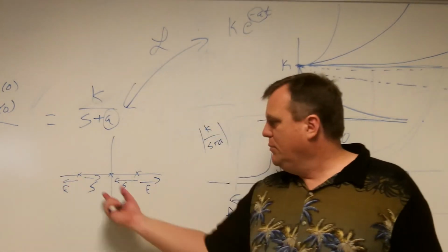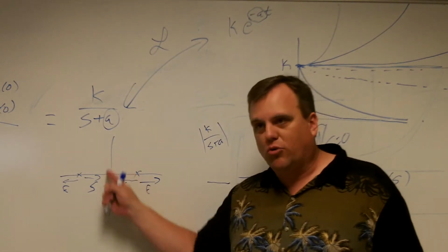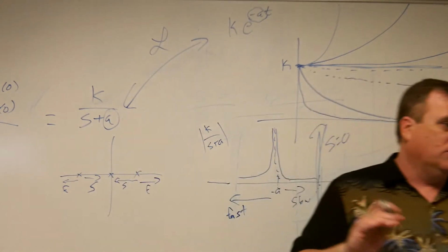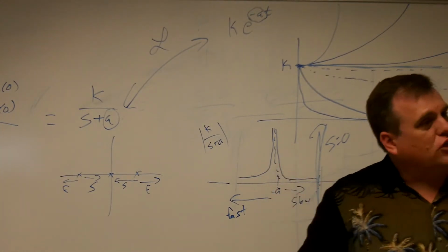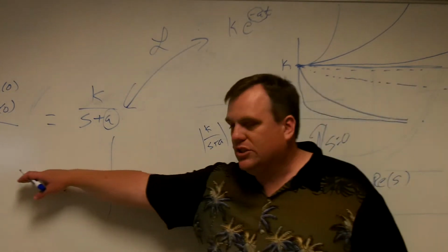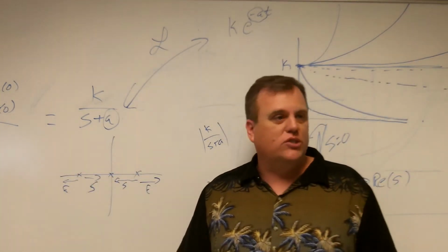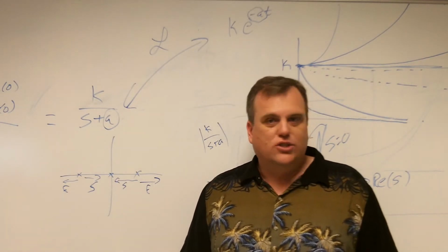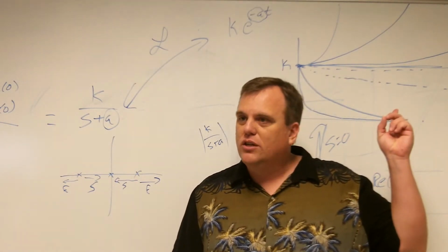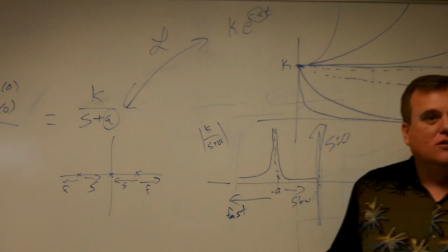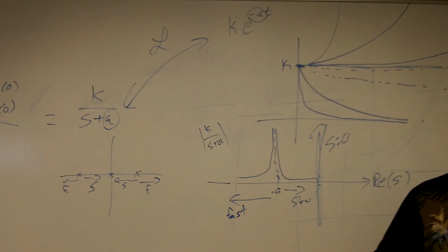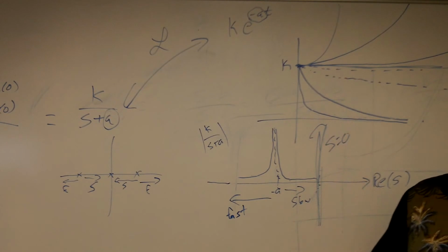So in between damping slow and growing slow, right at the point where they meet, it doesn't grow or damp, it just stays constant, never goes away. So you can now look at any single pole right on the axis, and you can immediately tell what the system does. You just look where it's located and you know what the behavior is. That pole will generate one of these curves. It has to. So realize you just analyzed the entire real line of the S-plane, and you can just stare at it and tell me exactly what the function does.